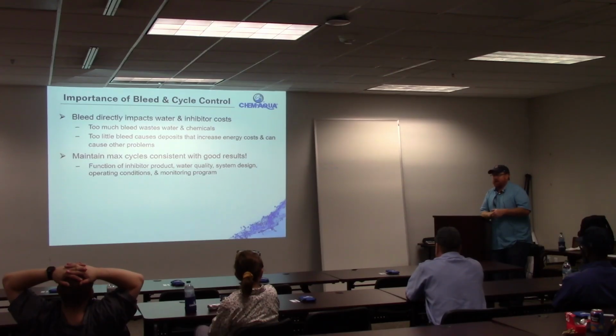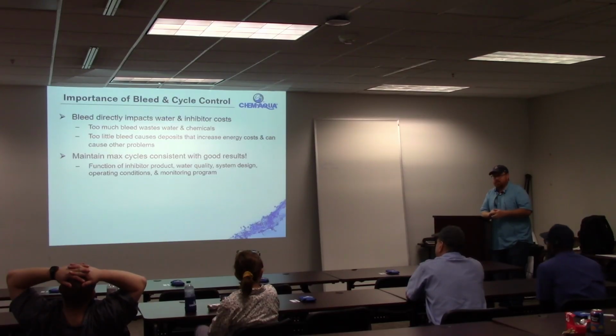If you don't have proper blowdown where you can control your cycles of concentration correctly, you don't have water treatment. It does not matter how much chemical you feed. Proper blowdown control is the most important, most critical thing about water treatment.